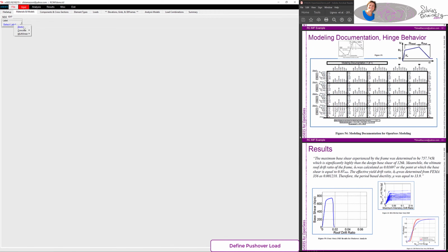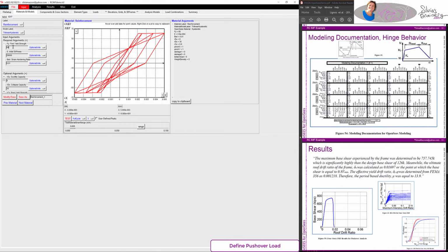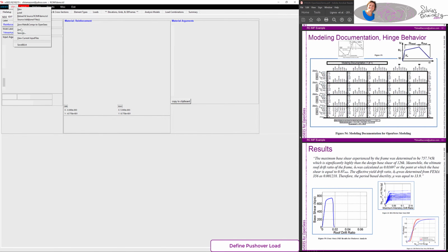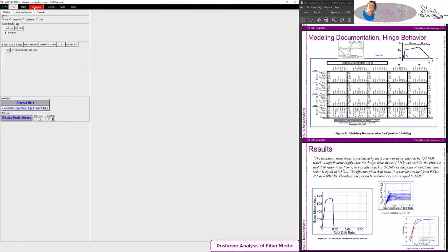And you go in, you select what am I doing? Oh, I need to update my reinforcement. This is when I realized that it was 67 KSI. So I can go in and just update my steel to 67 KSI because I saw that here. No big deal. Now I'm ready to run gravity.